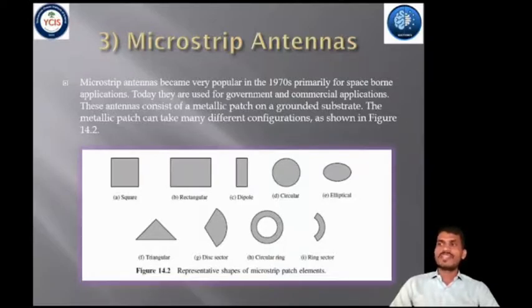The microstrip antennas are low profile, conformable to planar and non-planar surfaces. Simple and inexpensive to fabricate using modern printed circuit technology. Mechanically robust when mounted on rigid surfaces. Compatible with monolithic microwave integrated designs and very versatile in terms of resonant frequency, polarization, pattern and impedance.